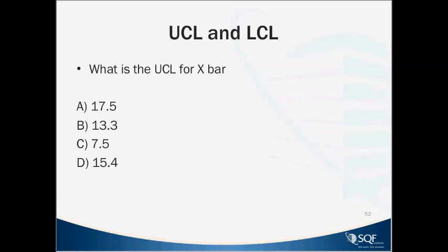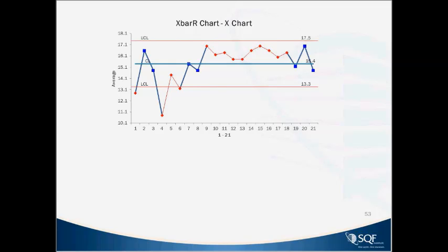It's good to know the different elements of those equations and the impact they have. In this case, the range, which is a factor of the variation in your subgroups, and obviously the measure of the variation in your process, is critical to the calculation of the upper and lower control limit for a control chart. And again, we're calculating this differently than we did for our capability, because these are averages of averages. We don't want the operator to have really wide control limits that make it very difficult to react to. So let's take a look at that control chart.